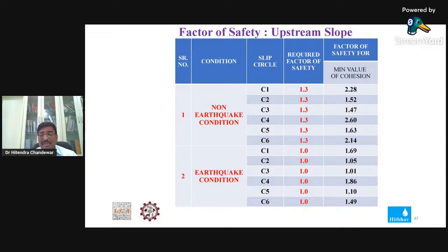So that means I have gone with a very critical design. I have not given any oversized section there. It is exactly neck to neck. I designed the earthen section neck to neck because my job is to work within 125 hectare. I have to give them the optimum size of the dam, optimum height, and optimum storage capacity. Their requirement of storage capacity was 37.44 lakh cubic meter.